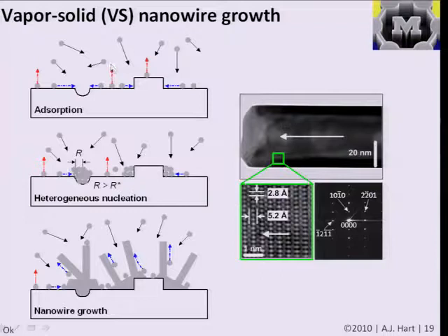And over time, the atoms start collecting in certain areas of the substrate. And in fact, substrates aren't often perfectly smooth, there are places that have little bits of roughness or little cavities. And because the energy change is greater if the atoms stick in a corner like so or stick in a little divot like so, you'll find that at locations that are rough, the atoms collect. They might stick for a longer time, and therefore if you surpass this critical threshold for nucleation, you end up forming clusters on the surface.